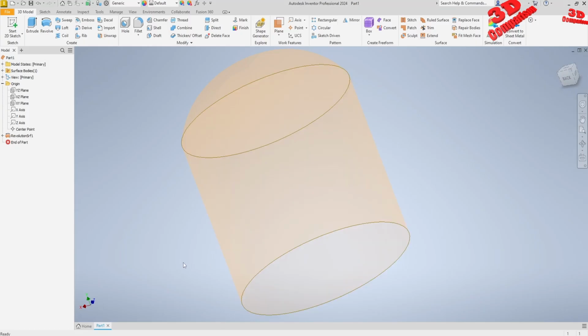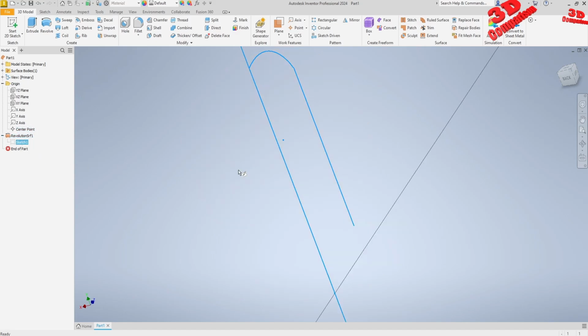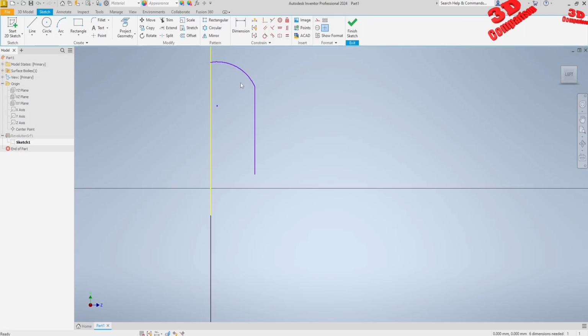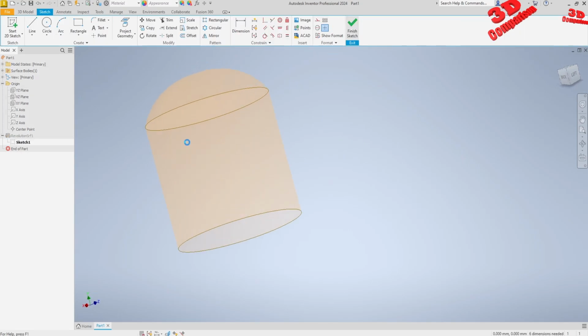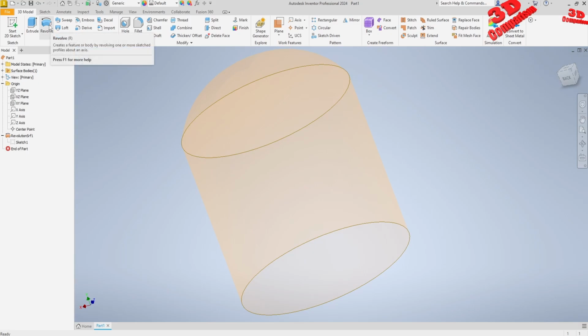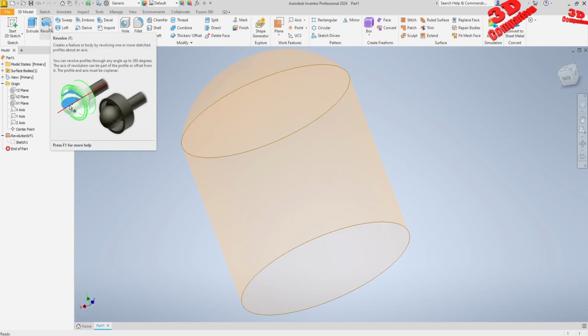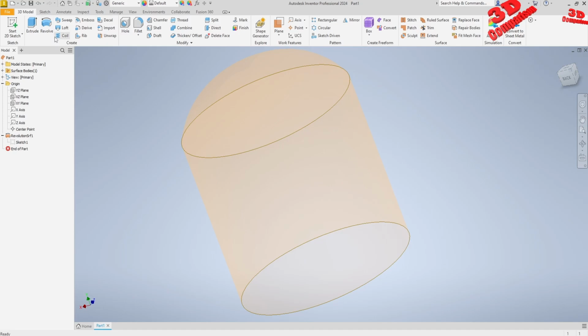Now let's jump to Inventor, and we're going to see over here within Inventor that everything will be nested under the 3D model. So regarding surface, we're going to have this functionality over here. But for example, over here I have the following sketch, which is just a simple line and an arc at the top, and this will be the axis. And since I added revolve, even though I used this revolve over here, since the sketch wasn't closed, it actually created a surface feature, and we see the naming over here. So this will be revolution surface.